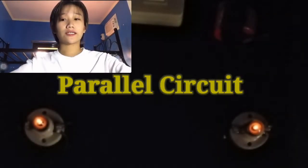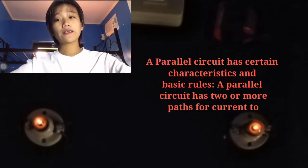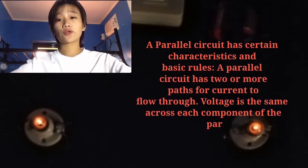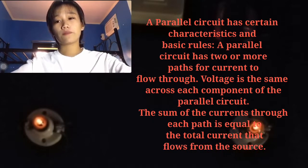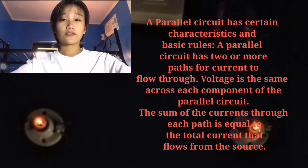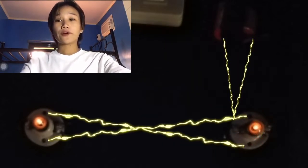A parallel circuit has certain characteristics and basic rules. A parallel circuit has two or more paths for current to flow through. Voltage is the same across each component of the parallel circuit. The sum of currents through each path is equal to the current that flows from the source. In a parallel circuit, all components are connected across each other, forming exactly two sets of electrically common points. A branch in a parallel circuit is a path for electric current formed by one of the load components.